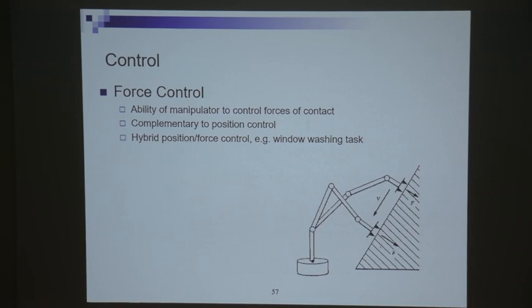Force control. Force control refers to the ability of the manipulator to control force or contact. This is complementary to position control. So you have position control, and on top of the position control, you may actually want to have force control.